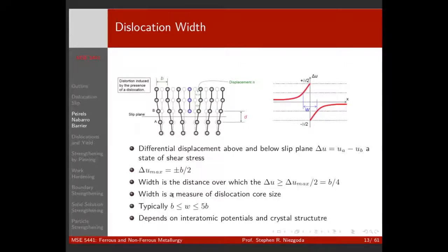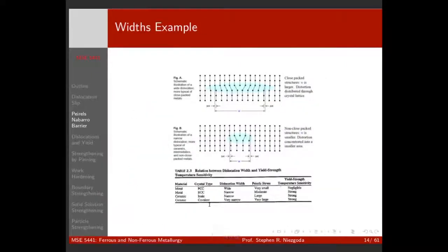Remember when we did some integration for the stress field and the energies of a dislocation, and we picked that r naught, and we said we're going to stand off and integrate away because once we get to the core, our displacements become infinite and everything goes to hell? Essentially, we're going to pick a value between 1 Burgers vector and 5 Burgers vectors, dependent on the system, for that r naught value.